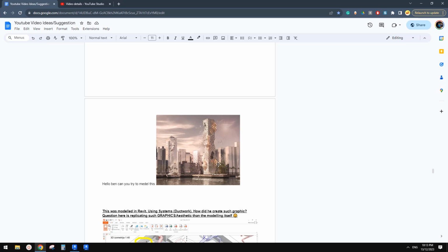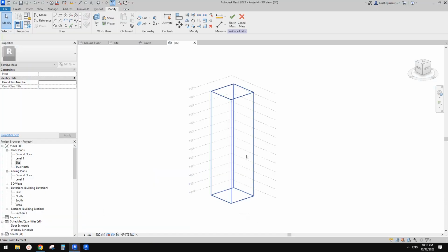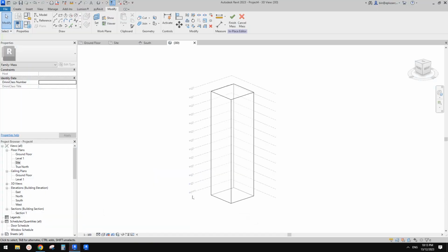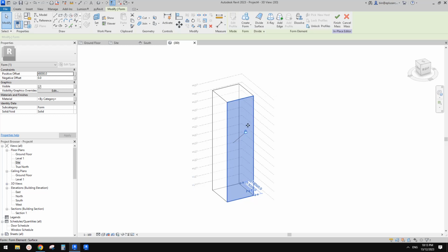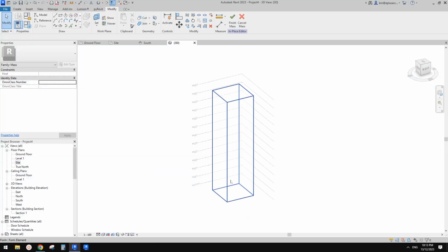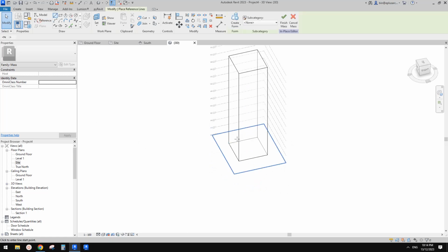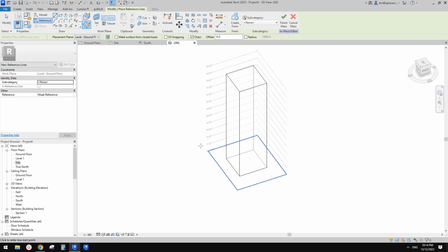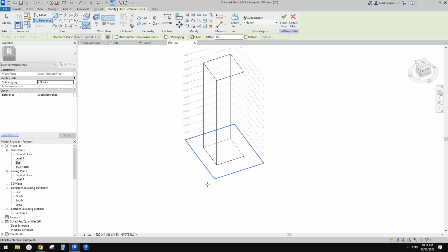So the next step is I'm going to create some void. Although these look like solid, right? So we can create this face, this flat part. Okay, so I'm going to use pattern based. So to get that surface, we're going to create some void, and for this void I'm going to try sphere. Okay, so let's do one. First, to create a sphere, we need to use it's like a revolve. We need an axis line, and then we need a half circle, right? So first we need to create an axis line, just a reference line.